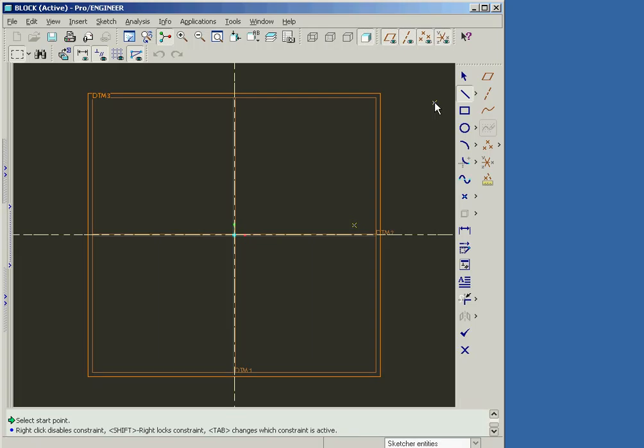We'll now select the Create 2-Point Lines icon in order to sketch lines that form a rectangle. A series of lines will be created as shown here by clicking the left mouse button at the end of each line. Notice that the cursor snaps to the reference lines when it gets close to them, and that Pro-E is automatically defining horizontal and vertical constraints as we sketch the rectangle.